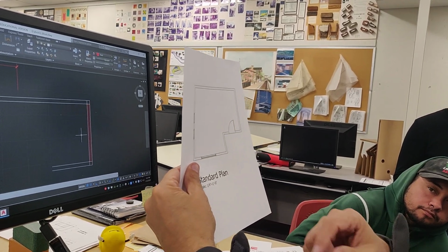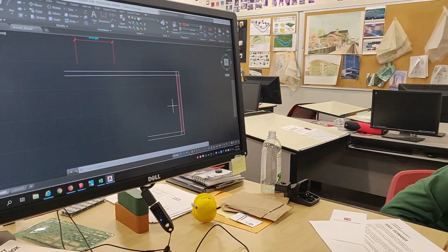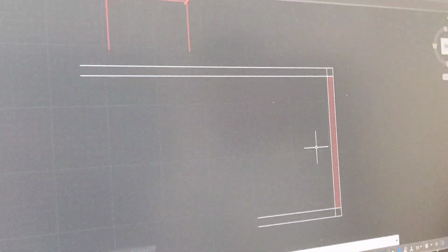By the way, you could actually do the hatch command, and you could select that, and what you do is you just select the inside of that. So let me do that again. Say, by the way, if you do something wrong and you want to get rid of it, Control Z backs you up, just like in those programs. Control Z, right, gets rid of that.